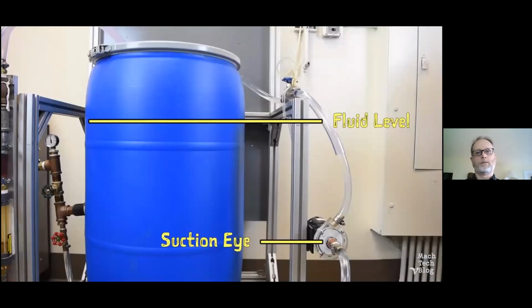So before the pump is turned on, the casing must be flooded with fluid, a process known as priming. And during operation, there must be a sufficient amount of available fluid under positive pressure at the suction inlet of the pump to replace the fluid which is being discharged. This is usually accomplished by placing the pump below the fluid level of the source tank.